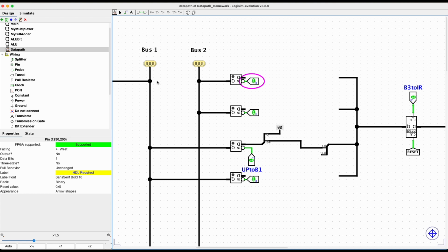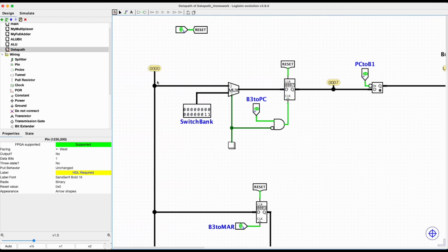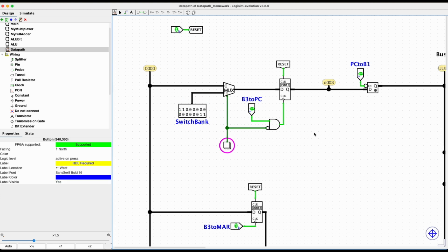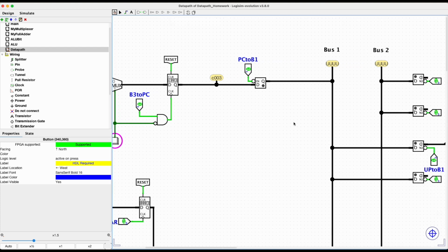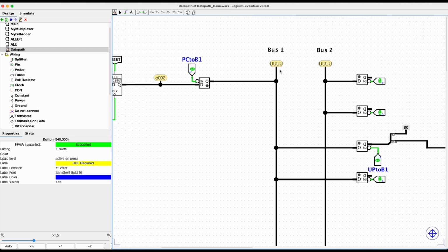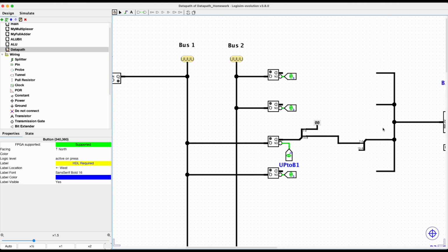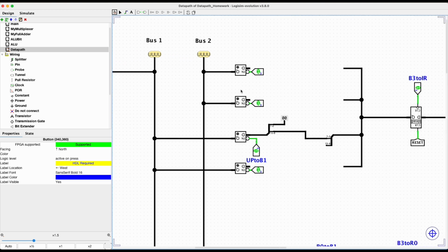Unless you go over to your program counter right here and put in something in the upper 4 bits. So this might kind of give away the answer and what you need to do for the target right here. But when you do that, then you should see C. Notice I got C in my upper 4 bits of my program counter. So we should see whatever's there up here, and then EAD down here. So the EAD should be in these 4 spots, and then the upper 4 of the PC should be in that spot.